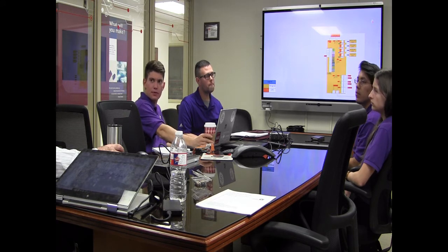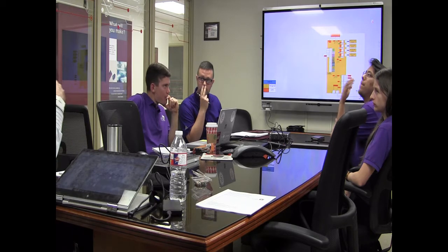Can you inquire what a PWM is set at, or can you only direct it to have a certain value? Can you read over that I2C what each PWM is? What the register values are? If I wanted to know what all of the PWMs were set at, can I do an inquiry? I haven't played with that much of the library to see if you can extract whatever register is being sent. Well, you're writing to a set of registers. Right. I guess the question is, can you read from those?